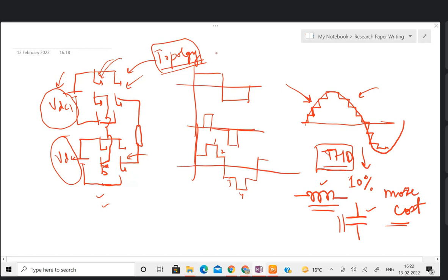And the second problem is about controlling this voltage waveform once you have generated it. Say you are working with an induction motor, where V by F control is there. You need to control V and you need to control F. Even V control is possible, so you have to change this voltage. So how to change this voltage? You need to adopt some modulation schemes.